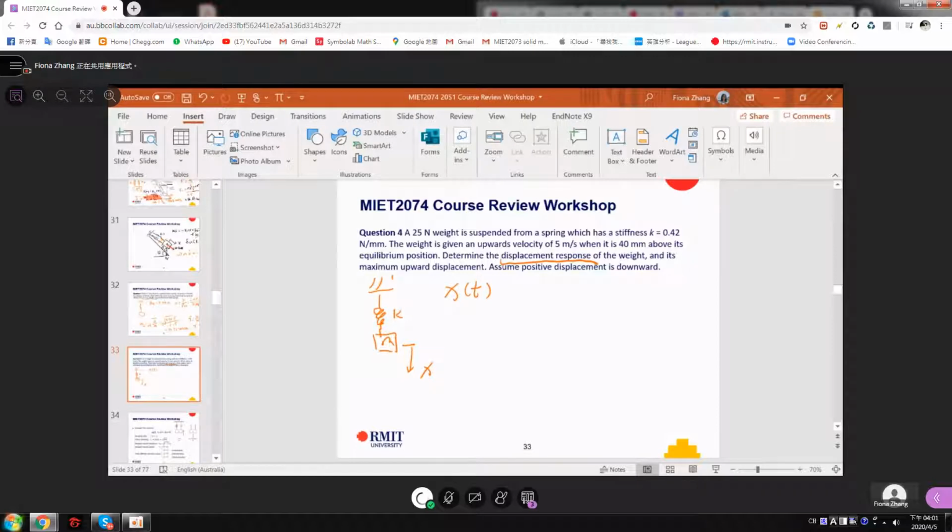Right, so you can see that this is undamped free vibration. So the general solution for the undamped free vibration is in this form, x equal to A sin(omega n t plus phi). Here I'm using A, but it doesn't matter. You can use C. Any symbol is fine, as long as you give it a form like this. Sinusoidal form is the amplitude and the phase.